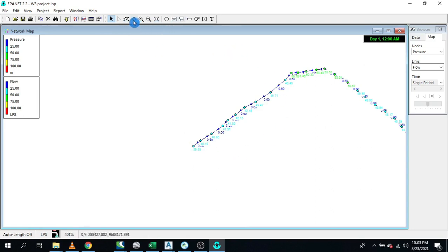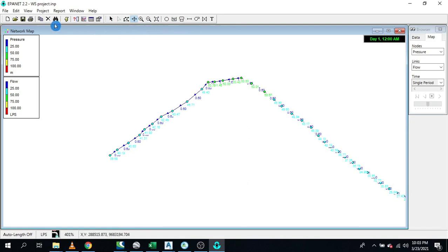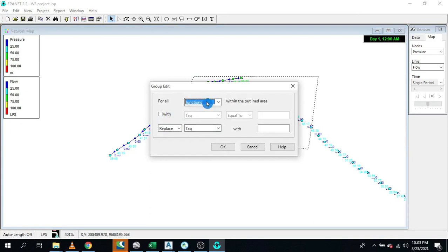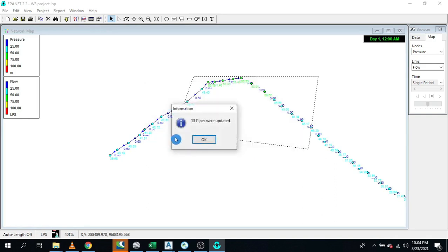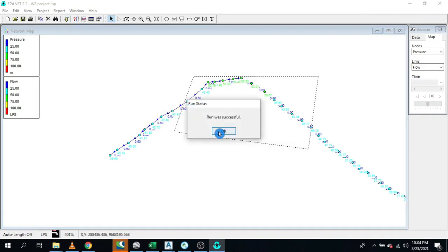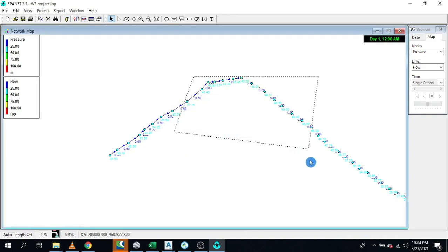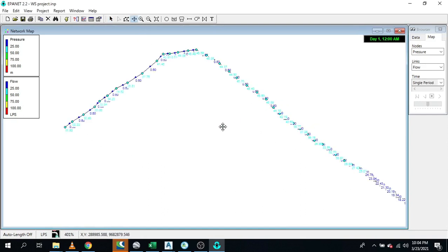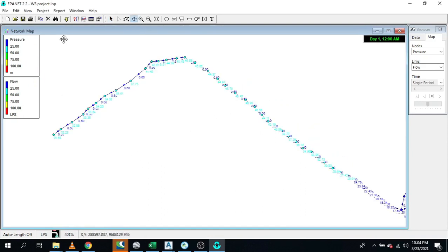That's the idea. Now let's again here, let's try to reduce some portion. Let's take it from here, at least this one, this portion again. Reduce pipes to 32. Group edit, then select pipes diameter again to 32 millimeter with internal diameter of 28. Click OK. From here, then run again. At least now we have 31. And again, let's try to reduce it again, at least to have 20 around there, 20 around something, 20.